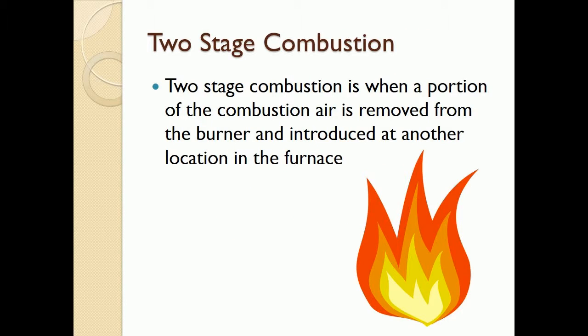In order to reduce nitrogen oxide emissions, two-stage combustion is utilized. Two-stage combustion is when a portion of the combustion air is removed from the burner and introduced at another location in the furnace. This reduces the flame temperature by expanding the flame.